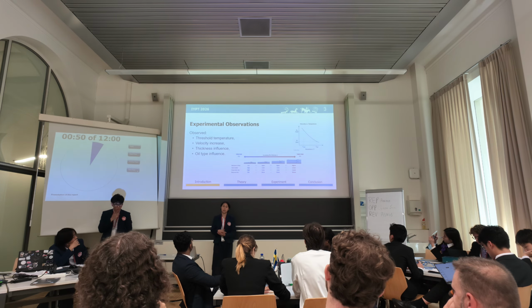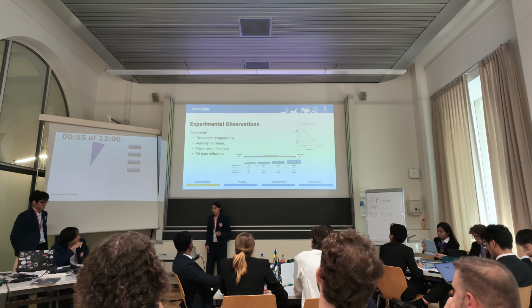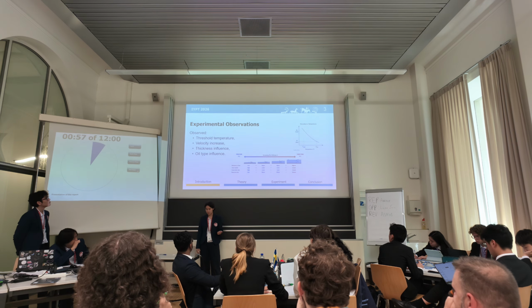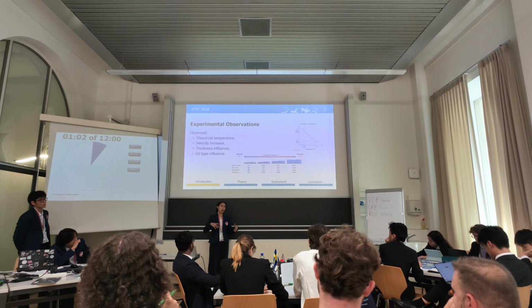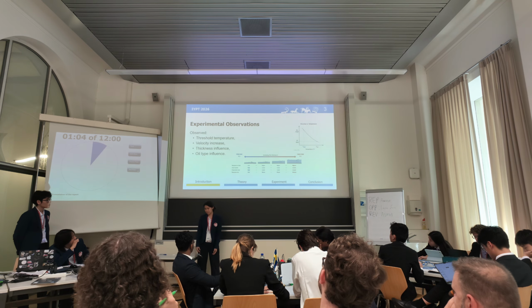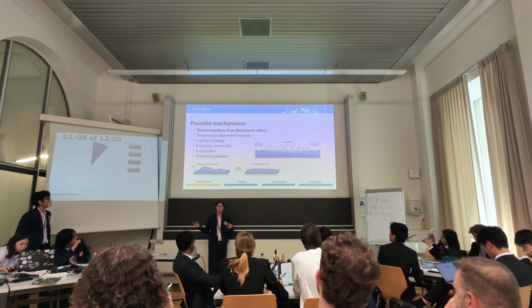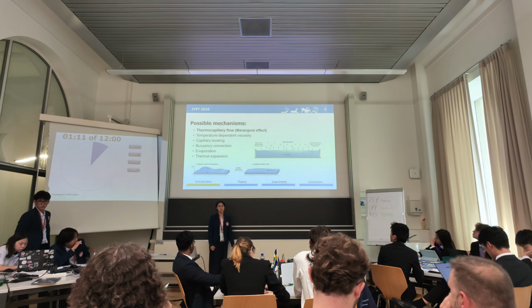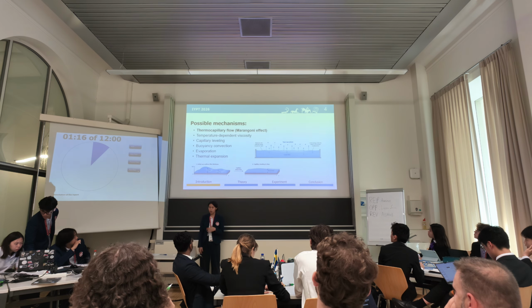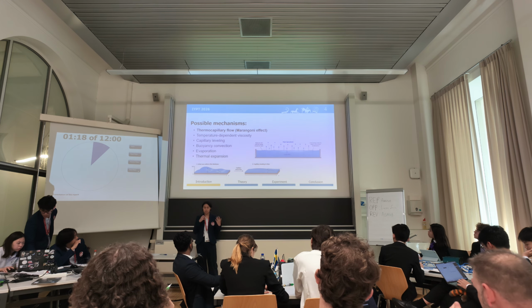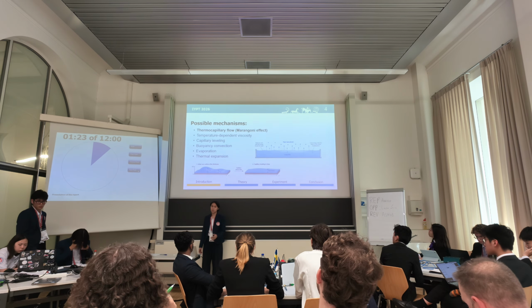First of all, I measured different parameters. It was the threshold temperature, the velocity increase, the thickness influence, the oil type influence. Later, I will describe how I checked all of these observations. So possible mechanisms, I use different physical concepts. My main one is the Marangoni flow, thermocapillary flow, the Marangoni effect. Also, I'm checking the temperature-dependent viscosity, the capillary leveling, the buoyancy convection, the evaporation, and thermal expansion.